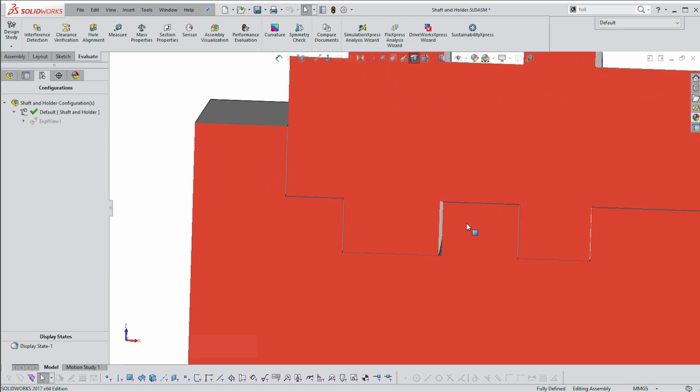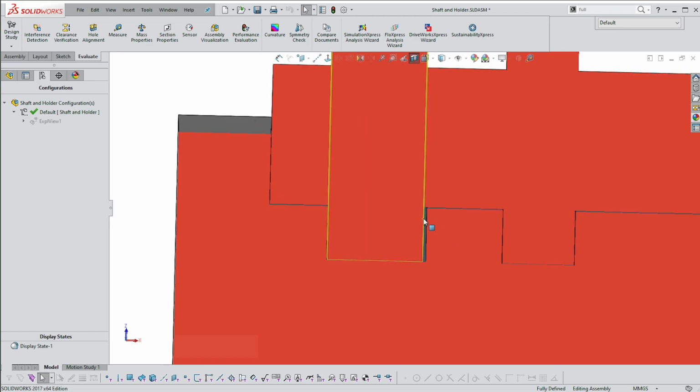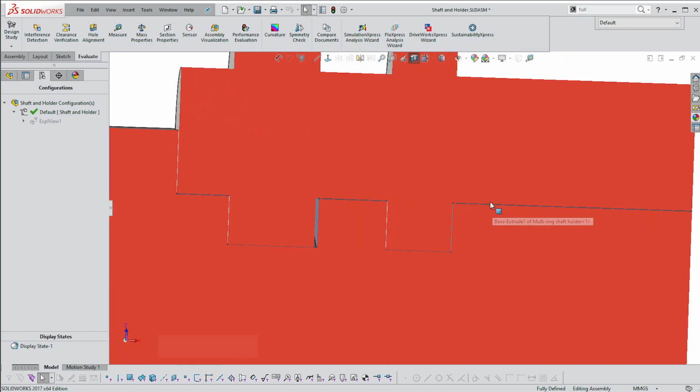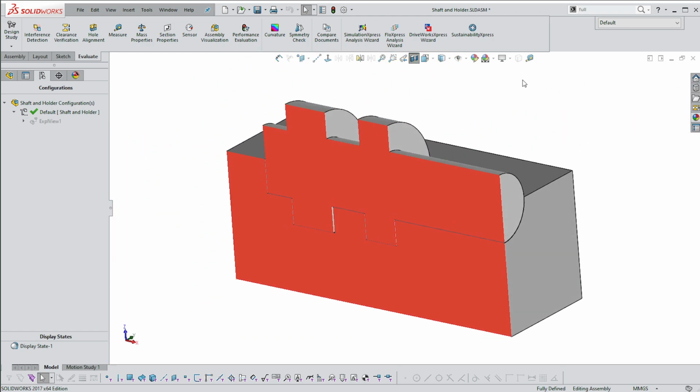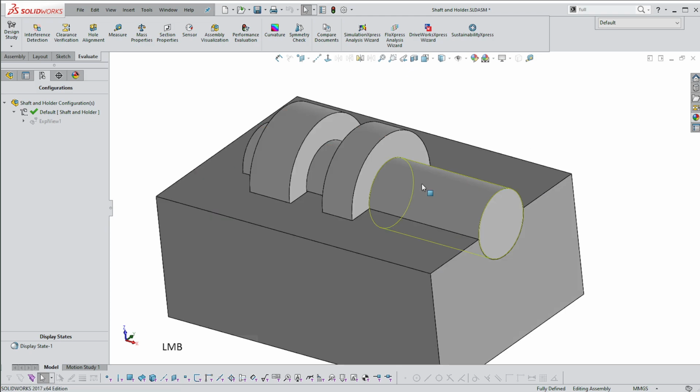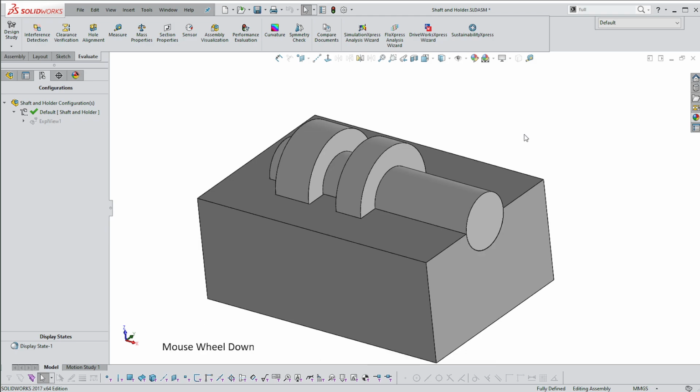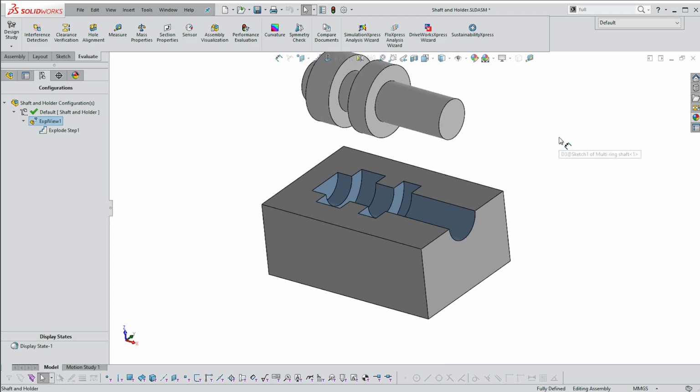So at the moment you see I've got a gap. Oh, I can see that one's larger than it should be. But I've given it a minimum gap of 0.25 millimeters, a very small gap. And that ensures that one part fits inside the other. So that's called a clearance fit. And if they interfered with one another, it would be called an interference fit.